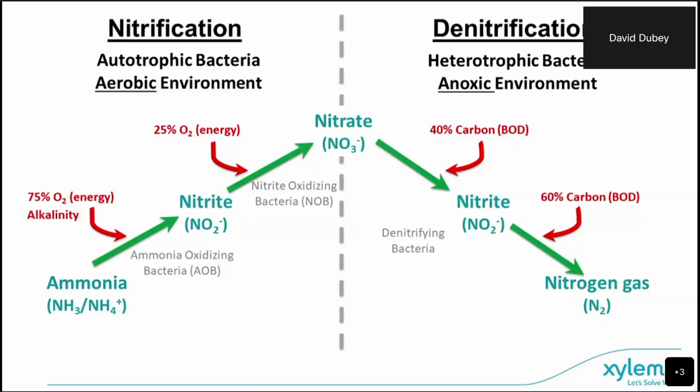So these are typically done in two separate steps in two different tanks: nitrification in an aerobic tank and denitrification in an anoxic, or without oxygen, tank.